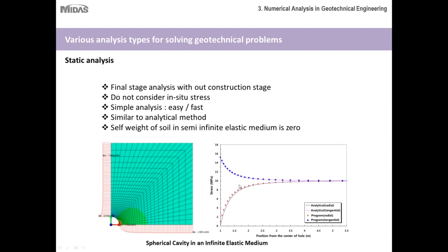If you look here, these are some examples of analytical methods that are used for static analysis. These are a good benchmark that you can use to make sure that your numerical analysis for static design went through all right. You can check these results against the results you got from your numerical modeling analysis, and since these are fairly simple and straightforward, you can have reasonable accuracy with them and compare them directly against what you have. If the results for your numerical analysis and the results you get from these 2 tests are within the same range, then you can say with greater confidence that your calculations are correct.